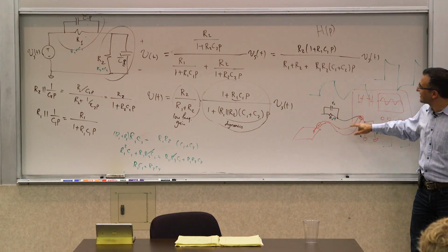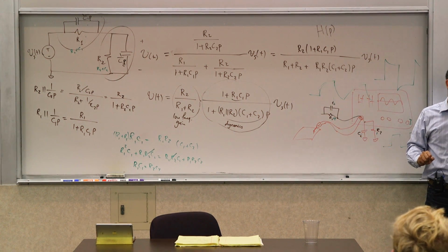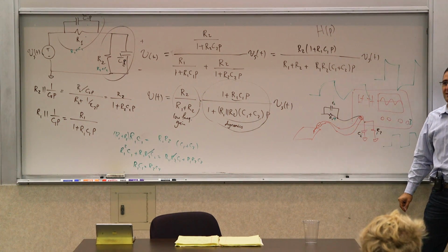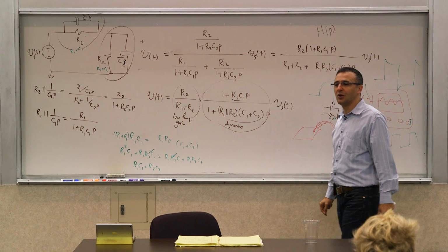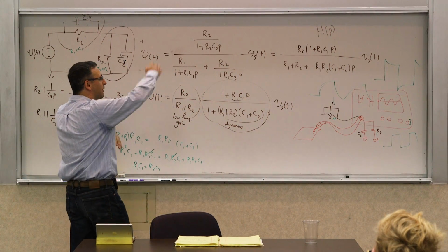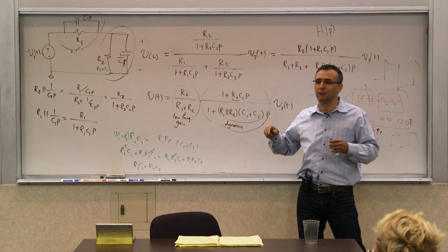And that means that at that point, this product has become equal to that product. And that's why your probe has a 10x, because you can see it's a 1 to 10 division. So all it does is just an attenuation of the voltage, but it's the better quality voltage, so you can always amplify it inside and make it look good, but you get the correct waveform.